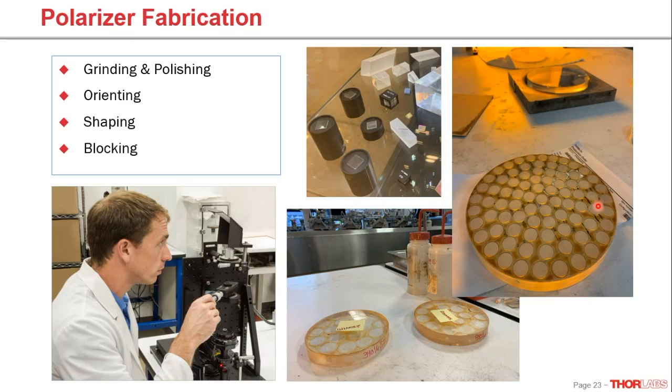On the flip side, in the case of wave plates, for example, we choose materials such as quartz, magnesium fluoride, or sapphire. And the reasons we do that are because, as I mentioned before, we want to maintain a low number of orders of waves for the parts to actually be shifted through. This reduces a lot of the sensitivity and also enables some of that achromatic balancing that we do as well. The sensitivities I'm referring to being both thermal as well as some very minor angle components and wavelength as well.